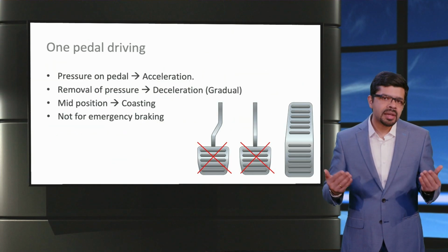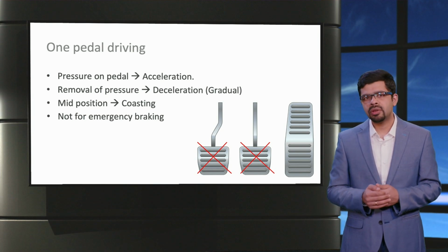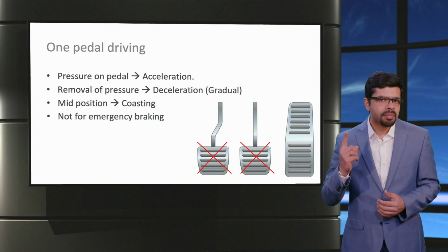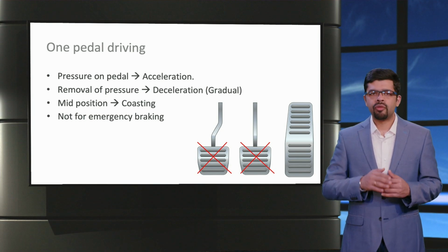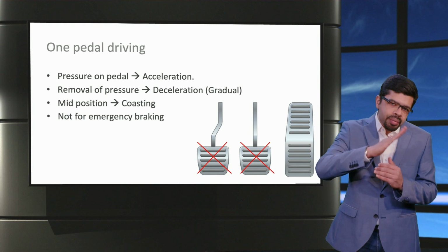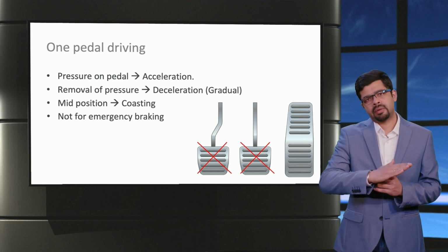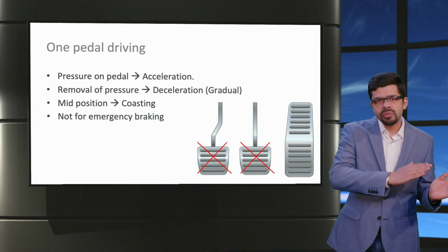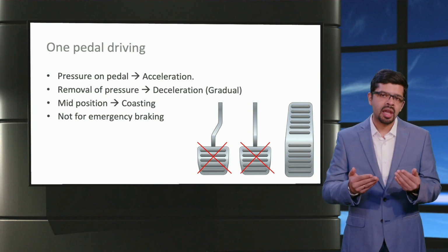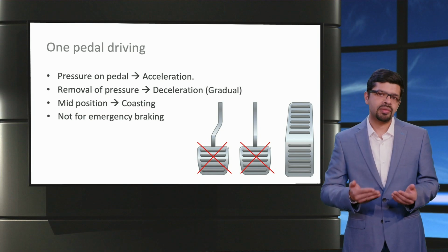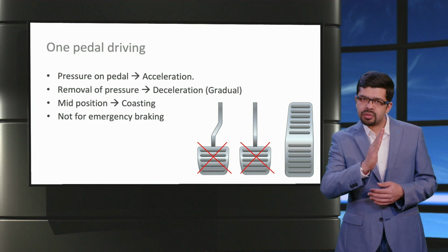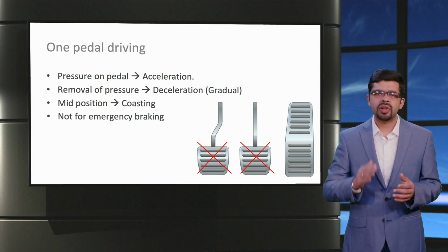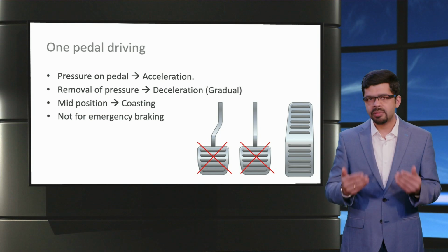An interesting implementation of regenerative braking by using only the acceleration pedal in the car is called one-pedal driving. For accelerating, a high pressure is applied on the accelerator pedal. But once the pressure is reduced, the vehicle will smoothly transition to coasting and eventually brake gradually when the pressure is further reduced or removed. However, one-pedal driving is generally used for gradual braking and not for emergency braking.